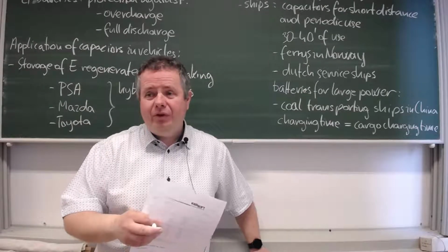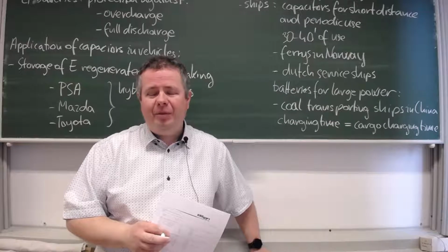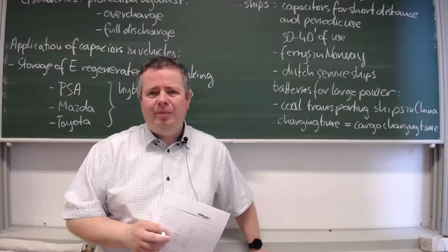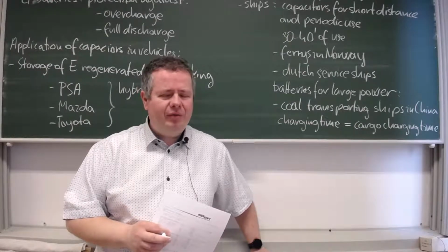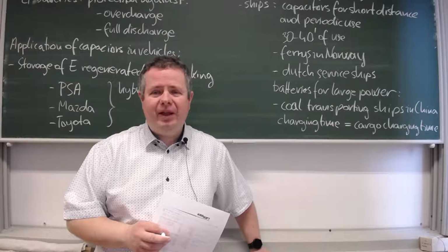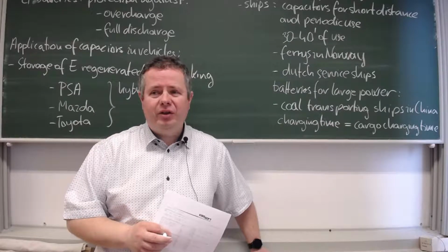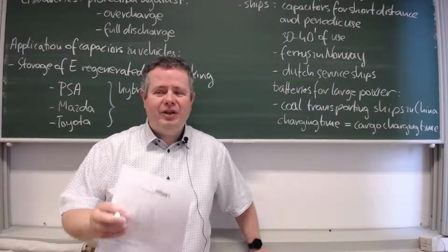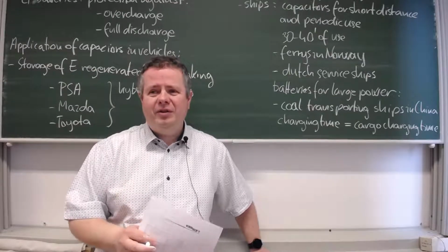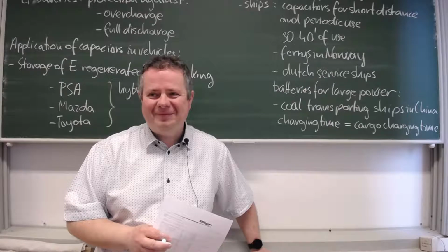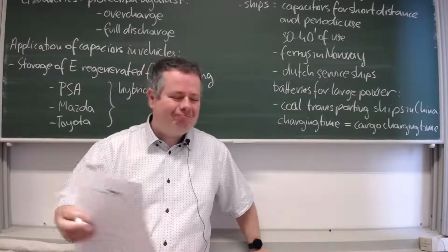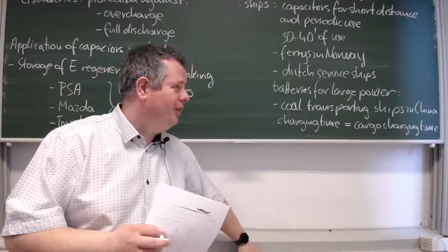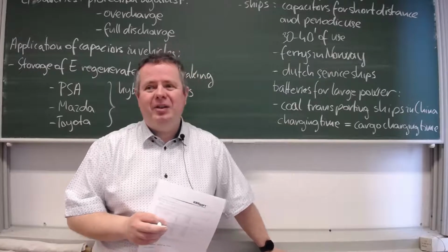Any question concerning this? So capacitors alone are not used too often, mostly coupled with batteries. But I have heard about buses, for example, and it was planned to have a charging station at each bus station. And by the time the passengers get off and on, it charges the capacitor inside the bus from 0 to full. Advantage, capacitor is cheaper than battery and also has less weight. Disadvantage, it cannot store as much energy as a battery.